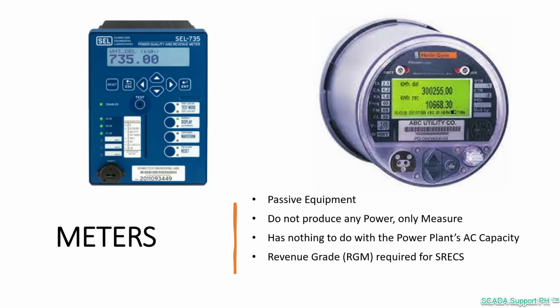Measuring AC energy delivered by a PV system can be broken into two main categories. You have your revenue grade and a non-revenue grade. A meter specified as being revenue grade is one that meets the requirements outlined in the ANSI standard C12.1 of 2008, and it is the one required for performance-based incentives such as SRECs or your solar renewable energy certificates.